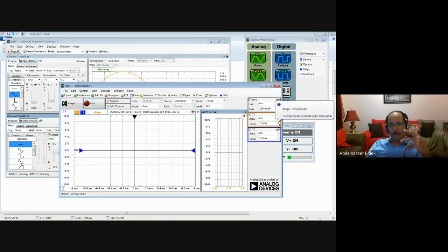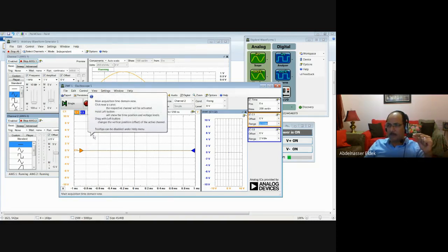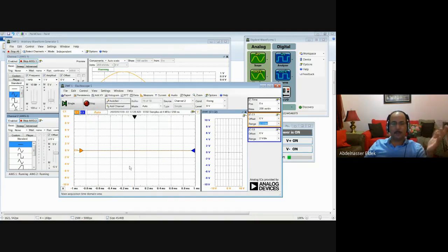If you want to compare, if you have 2 signals, you display them using channel 1 and channel 2, you have to make them the same number. So now, channel 1 and channel 2, each division has 2 volts. This is 2, 4, 6, 8, 10, and so on. And the timing here, this is the x-axis. So each division has 200 microsecond. So between this point and this point is 200 microsecond, 200 microsecond, and so on, a step.